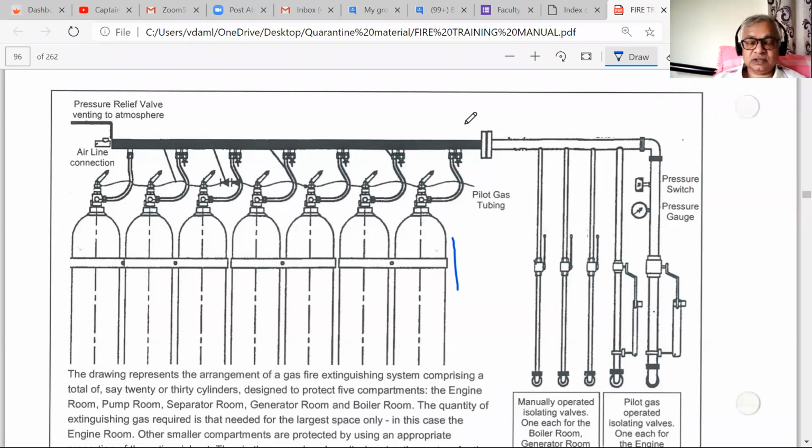200 bottles are not easy to handle. How do I know they have not leaked out? Normally, every dry docking, every 5 years, we check the weight of the bottles. Or there is a level gauger. This level gauger is a sort of ultrasonic device which you hold in your hand and take up on the side. When it finds the level of liquid, it will give an alarm, so he marks it. This point is marked.